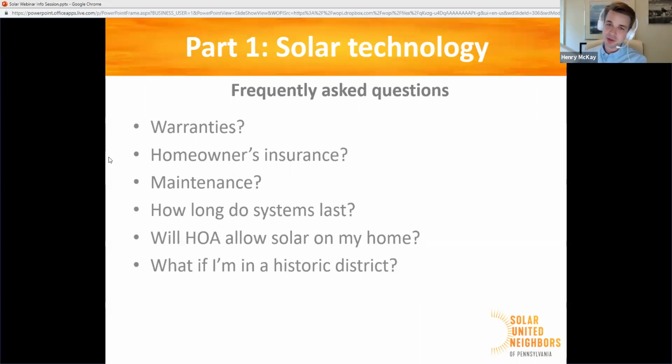And really, if your solar panels are covered in snow, you're only missing a couple days or even just a day of sunlight with them covered in snow. And really, it's January sunlight you're probably missing out on, not intense July sunlight. So you're not leaving a lot of energy on the table if you're leaving that snow on your panels. They'll even work with some snow on them. It has to be a fairly thick layer of snow for them to not work at all.